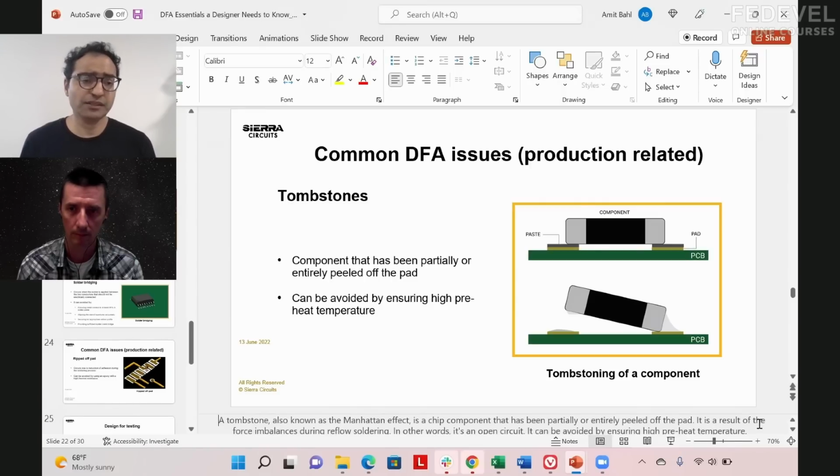Then after manufacturing, well, I should say in your requirements, flow down requirements to the vendor, you have to say, no changes to data are allowed unless approved by me, approved by the designer. So then the operator in manufacturing, whether it's fab or assembly, will see that note and then won't do what they usually do. They'll have to get a reply from the customer. And in which case, as a customer, you would now know what are the changes that are happening, and you can explore further.